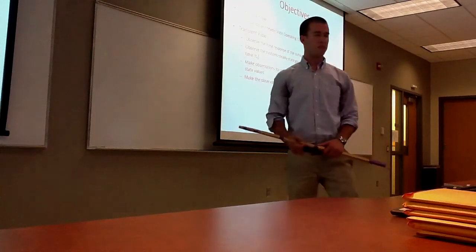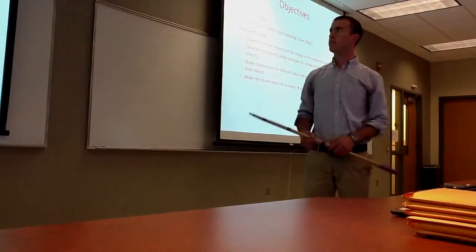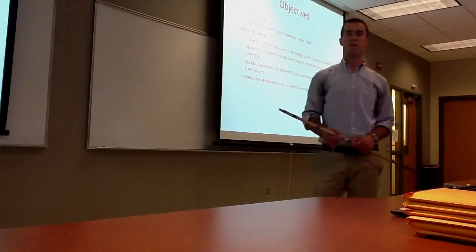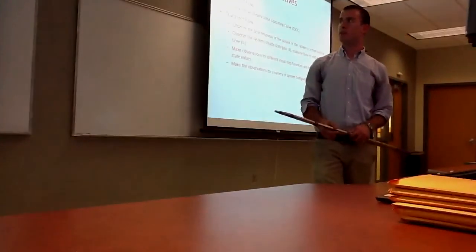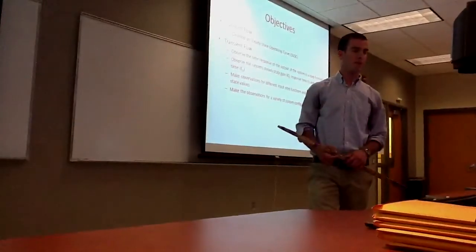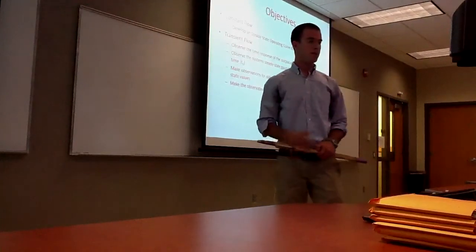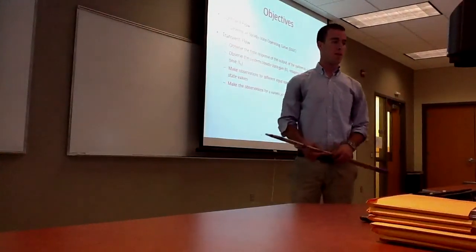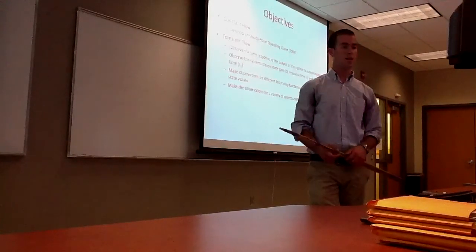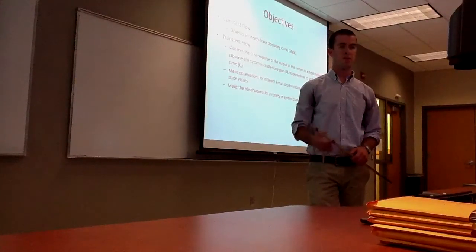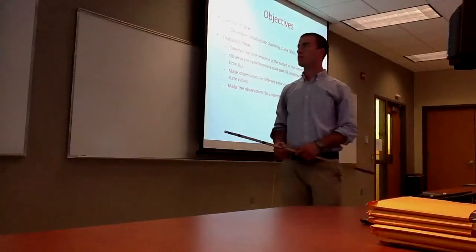The objectives of this experiment were to achieve a steady state operating curve in order to explain more about what output you can get from the input, and also in the transient flow, find out the system's dead time and how long it takes for it to respond when you do the step up with the inputs.